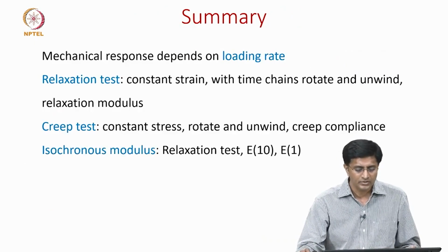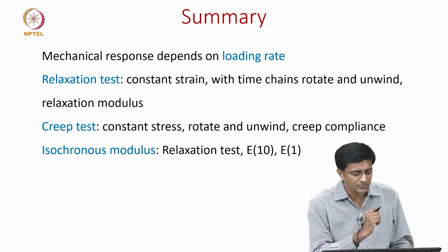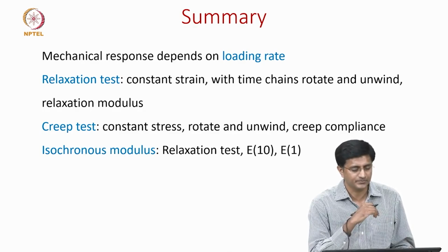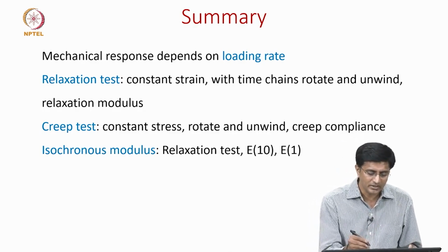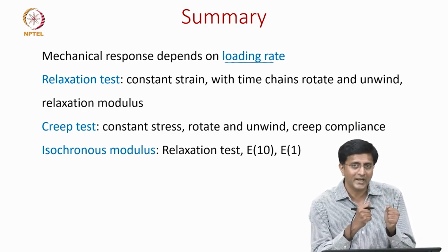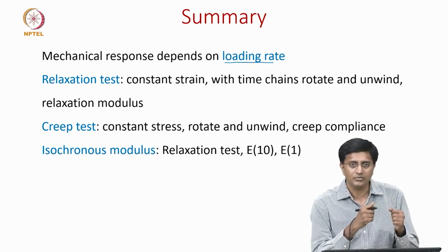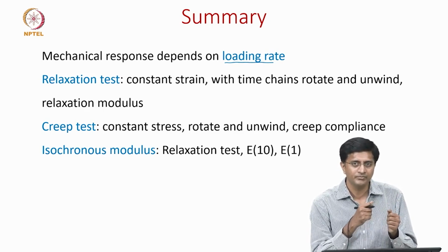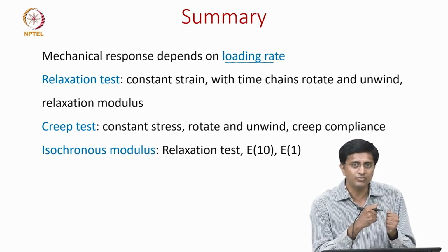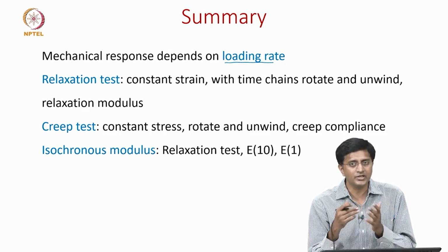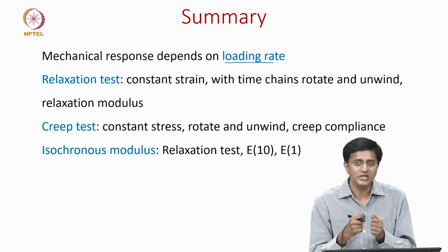Now, let us summarize what we have discussed in this video. We were discussing the time effects of polymers. We started by saying that loading rate is very important when we design or plan a test. With PVC we have seen that brittle behavior is shown when the loading rate is very high, but when the loading rate is low, then we see a ductile behavior.